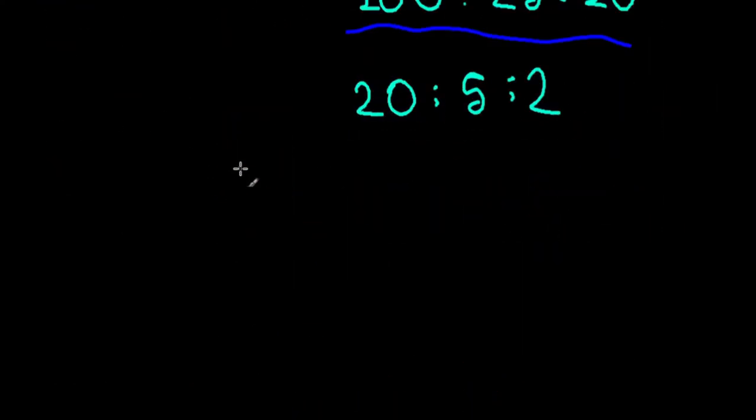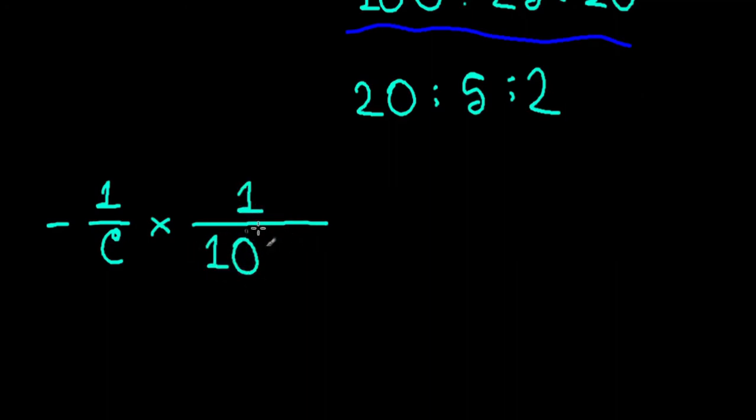I'm equating the first coefficients there. So negative 1 by C times 1 by R1, which is 100 times 10 to the 3, 100 kilo ohms, that I picked as R1. I should have probably written that. So this is 10 to the 5. It's going to be equal to -1.